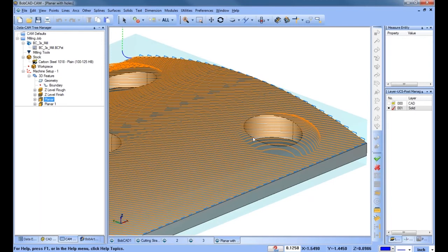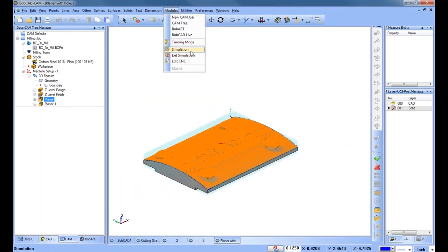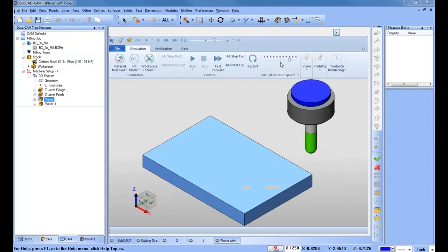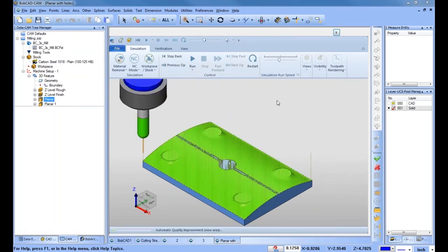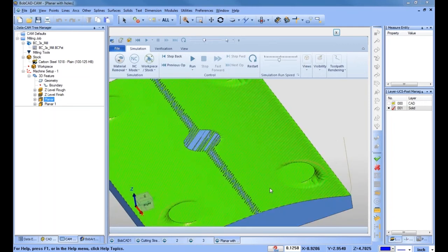But you can see how with the ignore holes, the tool is kind of running up over it. But I don't know, we would kind of want it to go past that edge there. That really is not the ideal scenario for us in this example. If you see with the ignore holes on this part here, that's actually leaving toolpath there, and then when you factor in the radius of the cutter, you know, not the most ideal scenario.